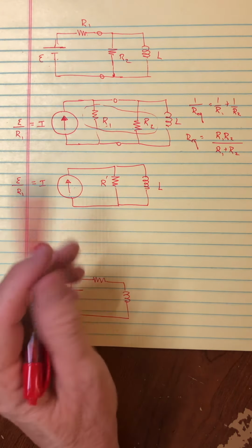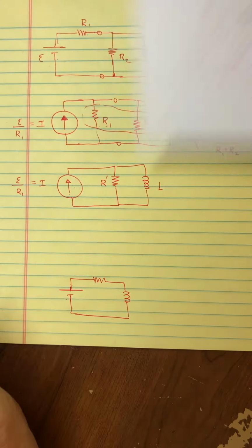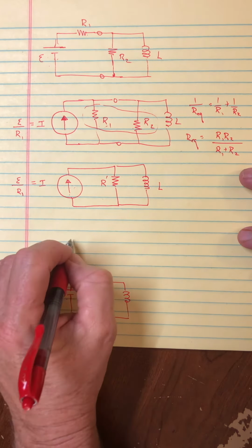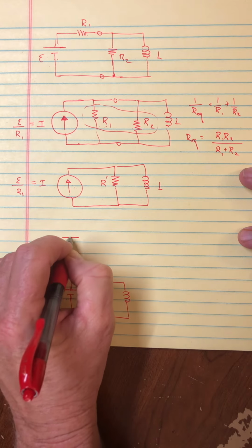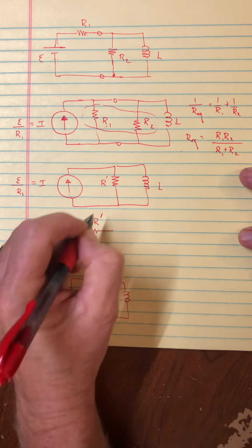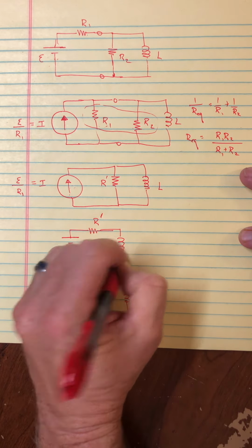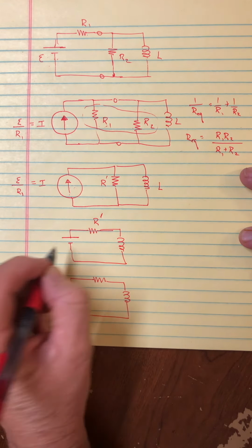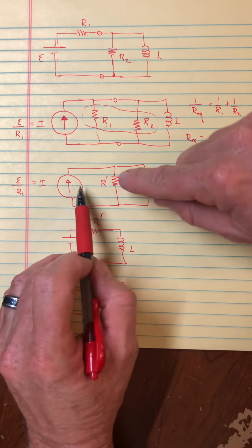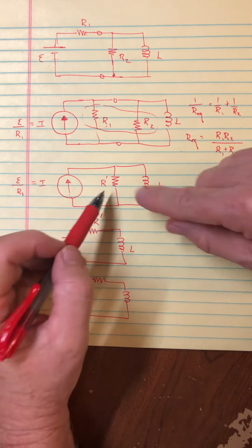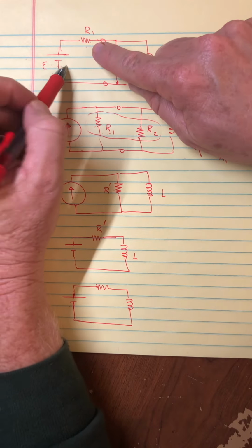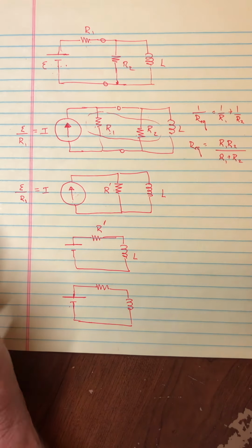So I had to do something to get those two resistors to combine. That was the strategy here. So now let me do that. Let me go back to a constant voltage source with the resistor in series. Right here, I'm doing the reverse of this: I'm taking a resistor that's in parallel with a constant current source and putting it in series with a constant voltage.